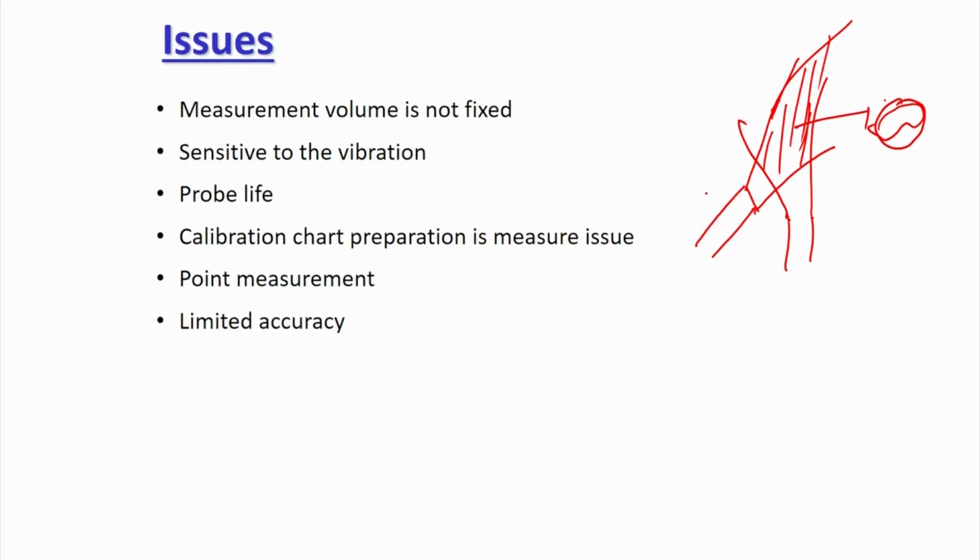But in the case of solids, it will never be only pure gas, or only pure liquid. It will be a combination of gas and solid in this way, and that change in the gas concentration, solid concentration will change the intensity, which will be recorded on the photo detector. Therefore, you need to do multi-point calibration.